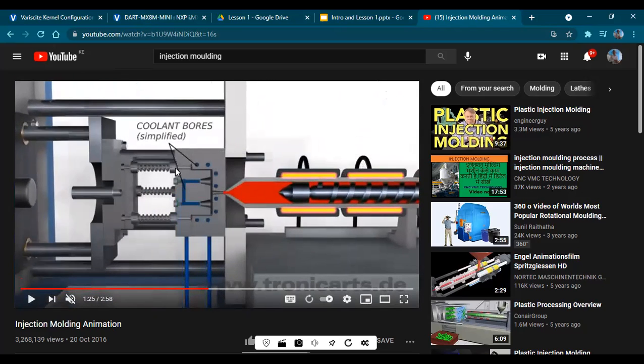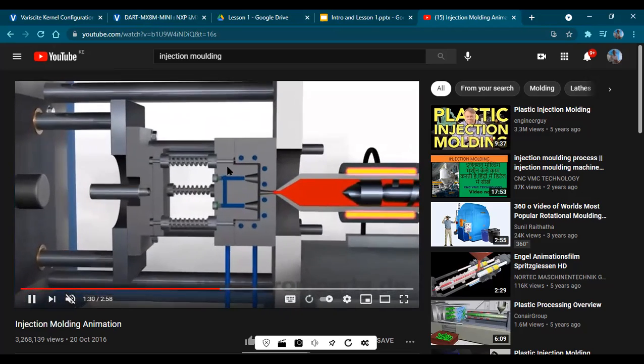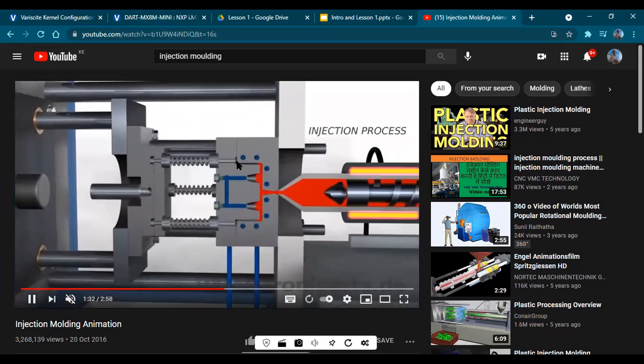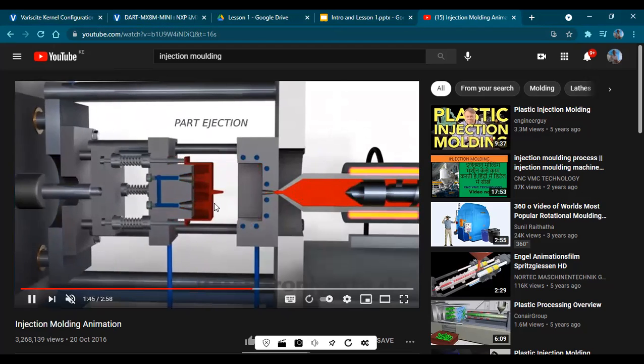where you have what is called a mold. A mold is a template. It's like a template of your design, or a cross section of how your design looks. If you look inside here, the plastic is fed in, and it fills in the space, creating your object, which in this case can be a cup, a basin, or whatever plastic part you want.